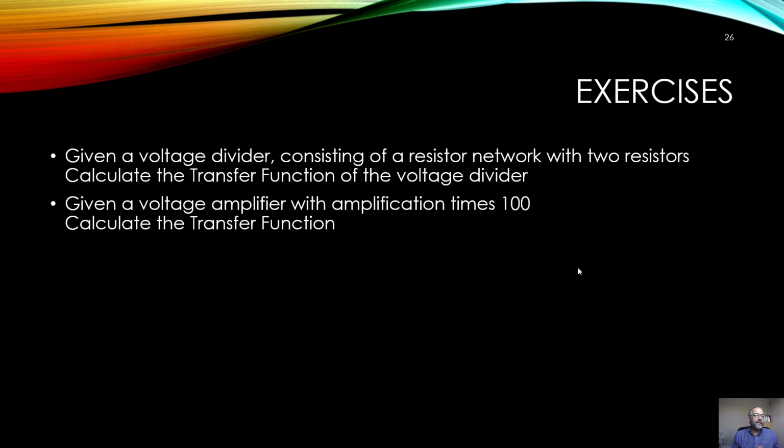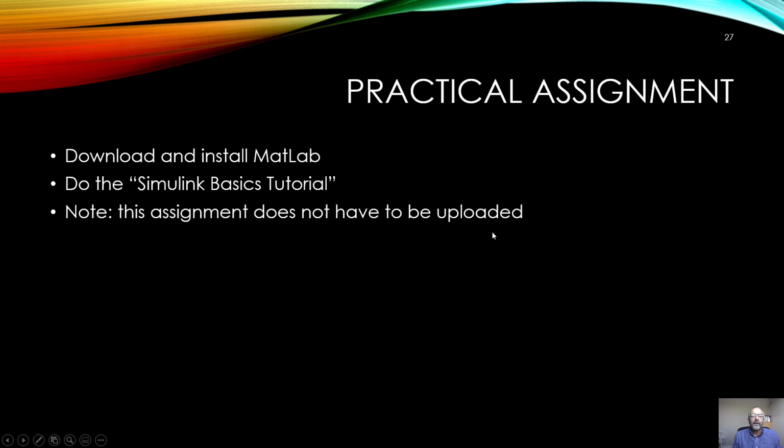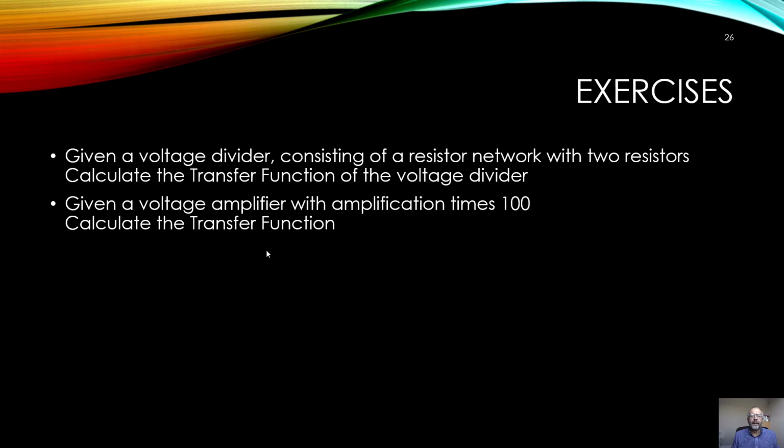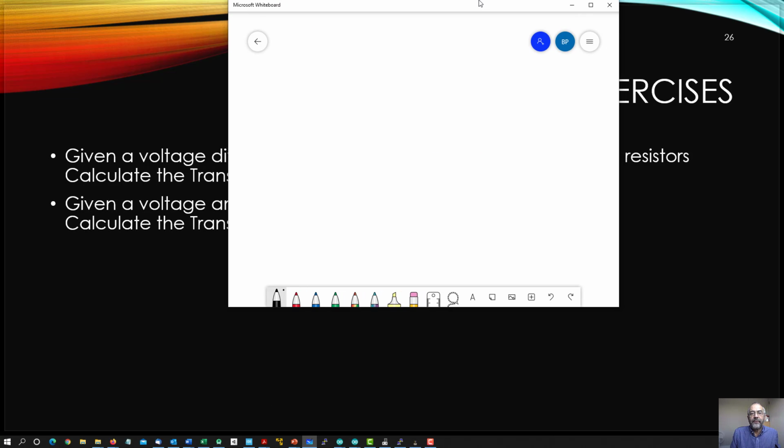Okay, here are some exercises which I will leave to you, and we can do them in the live lecture maybe. Here are some exercises. Let's have a quick look to see what is meant here. The first exercise is: given a voltage divider, I hope you know what it is. It's a network of two resistors. Calculate the transfer function for that voltage divider.